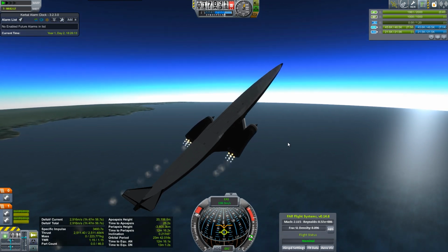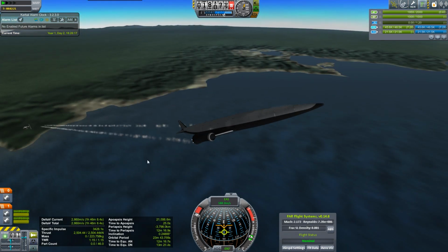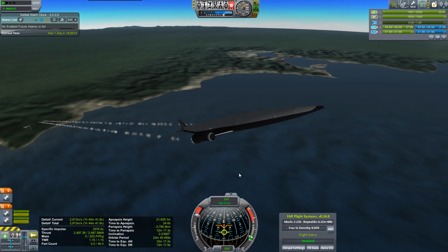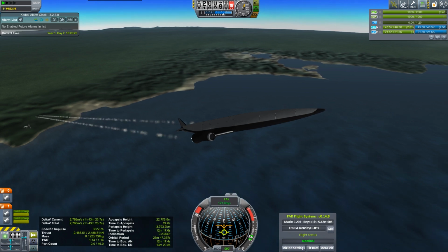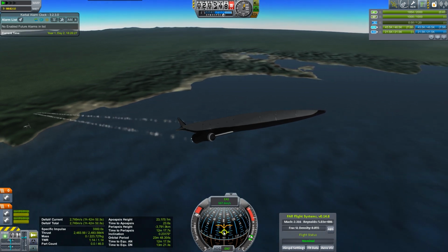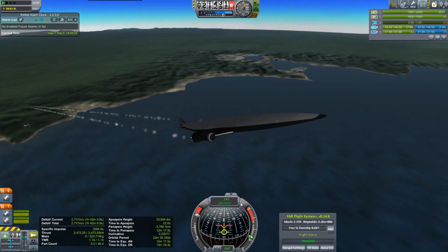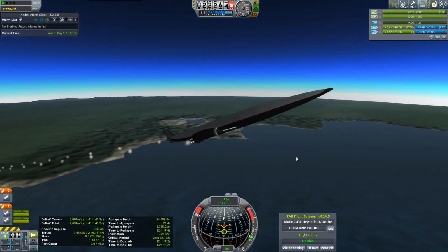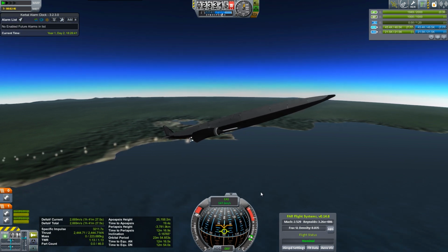This is just trial and error, doing lots of different iterations of this vehicle in this setup, and that is what seems to work. Okay, so there's 19 kilometers, and not touching the pitch, we gradually see our direction vector getting down closer to that horizon. Okay, let's start pitch trim forward a little bit. Very, very small changes are all that's called for here. Also trying to correct the inclination error. Do a little bit more pitch forward.